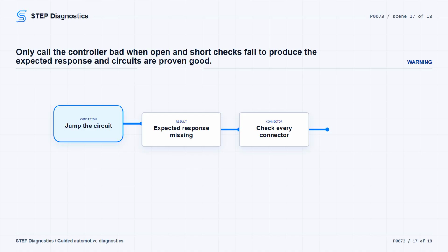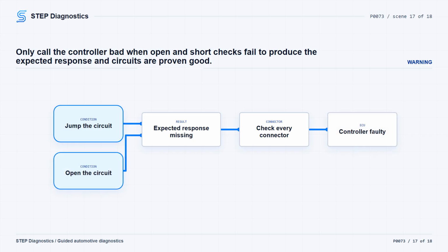If the actual sensor temperature can be acquired or reasonably estimated, measure resistance across the sensor terminals and compare it to the table. If no table is available for the sensor being tested, connect the electrical test kit to the harness connector, switch to adjust, turn the ignition on, and slowly change resistance while watching scan data. If the temperature or voltage value changes as resistance is varied, that points toward the sensor being likely faulty.